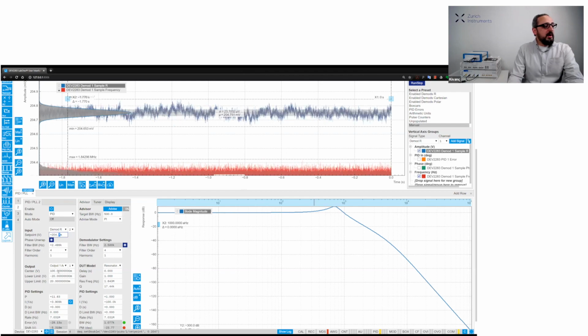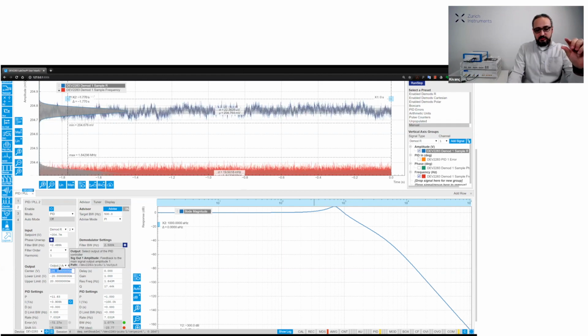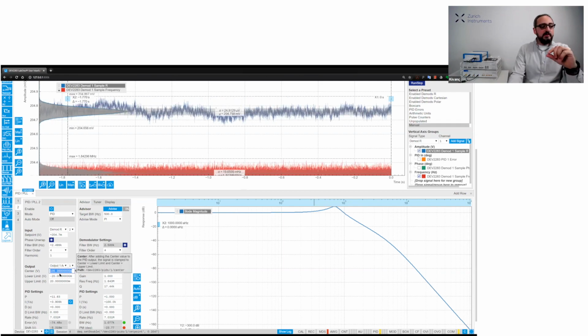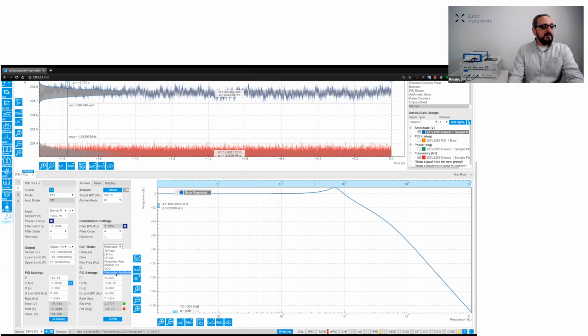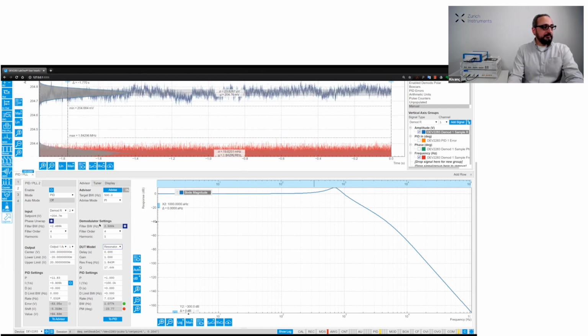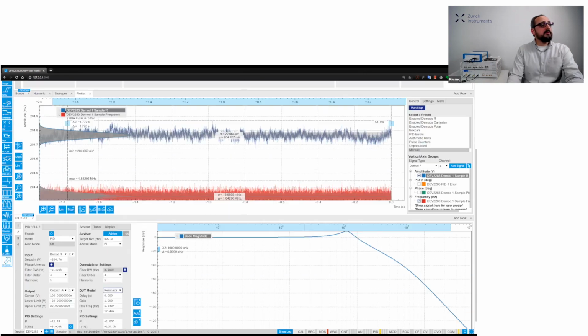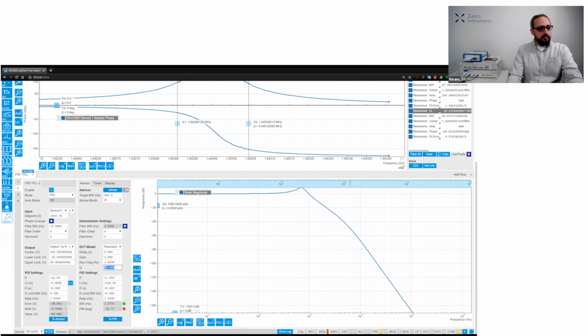We are already driving around 100 millivolt center amplitude, and this will be our output value. So we will vary the amplitude that we drive this device with. And in this case, our DU2 model should be resonance amplitude. And again, we need to write down the correct resonance frequency and Q factors. So that's why I go back to the sweeper. And this is the Q, around 19.27 K, and then the center frequency.